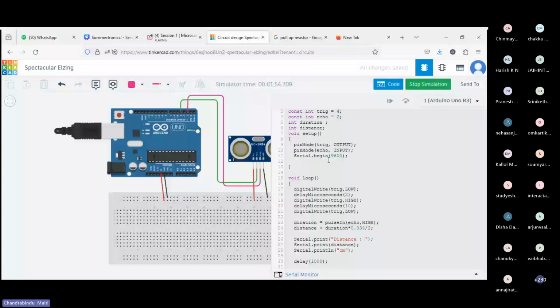The calculating everything is done in the Arduino, and then it sends the data to us. We are printing the data on our computer. In this case, we are using a simulator, but for real, it is happening like that. So it connects the Arduino with our computer and the transfer is happening. That is 9600, the baud rate.